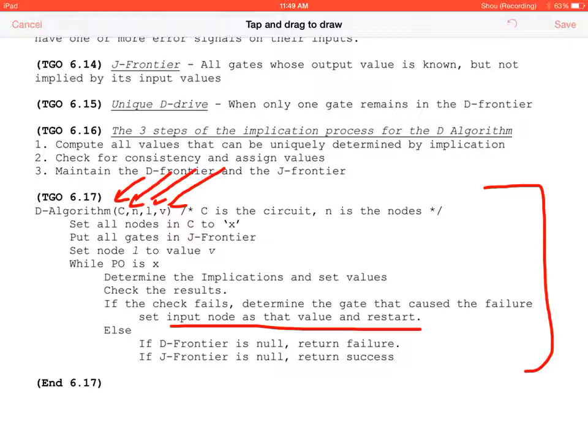If you're doing an ATPG algorithm and you determine that there are certain nodes that can't be detected by a test vector, then you actually have to physically test every single chip of those specific nodes. However, by determining the set of input vectors, you can just run those, and if they all work, that means you know 98% of the work is done. And then you just have to physically check 2%, instead of having to check 100%.